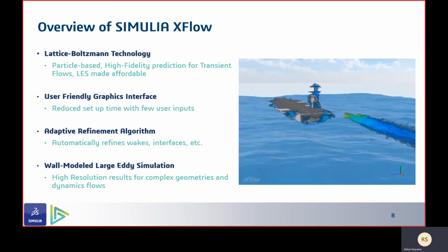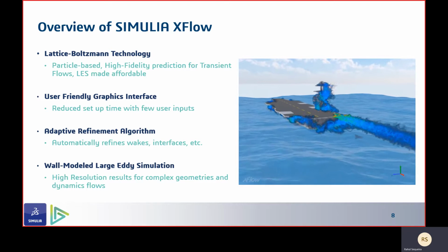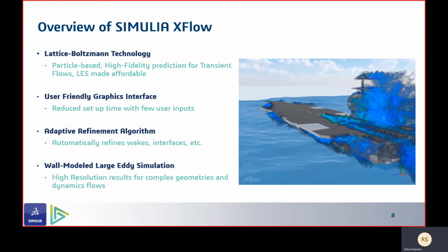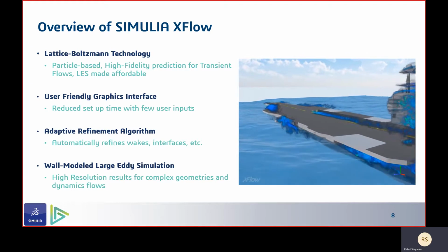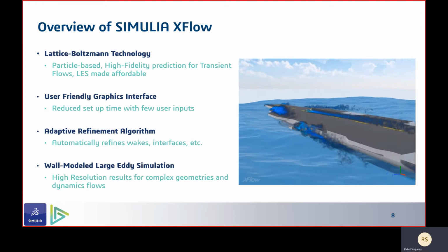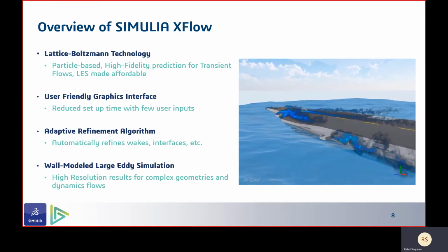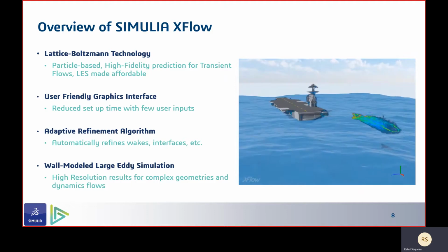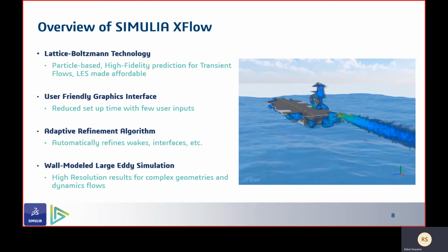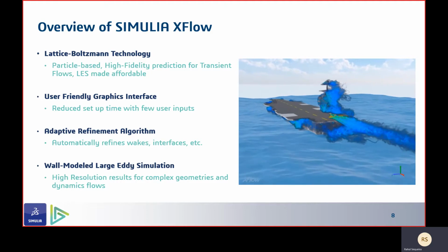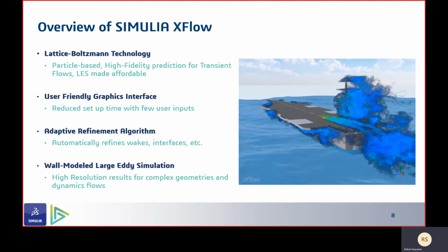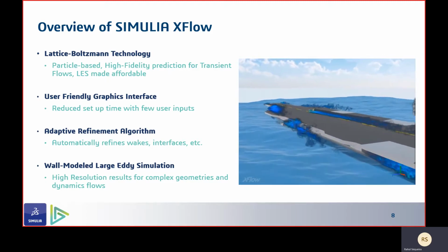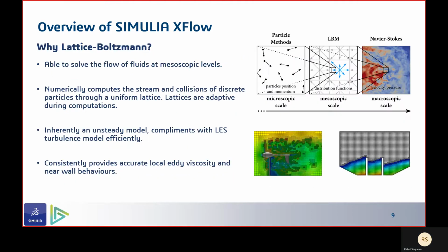Coupled with a user-friendly graphical interface, it helps users reduce the time needed to set up their CFD solutions. The beauty of XFlow is that it includes an adaptive refinement algorithm. It automatically refines the wakes and the interfaces of the parts depending on their positions. The last important thing is that XFlow is also equipped with the WALE large eddy simulation turbulence model. With this model, it is able to provide high-resolution results for complex geometries and even complex dynamic flows.